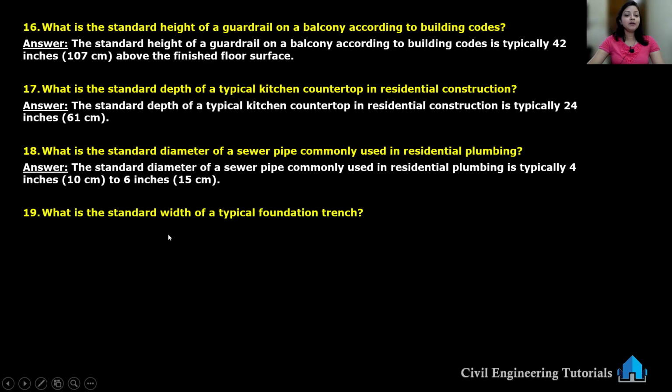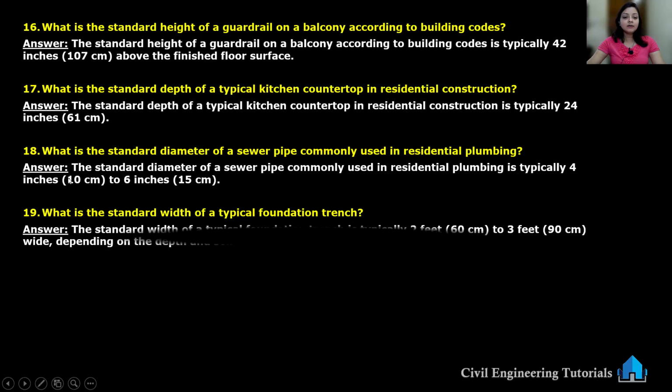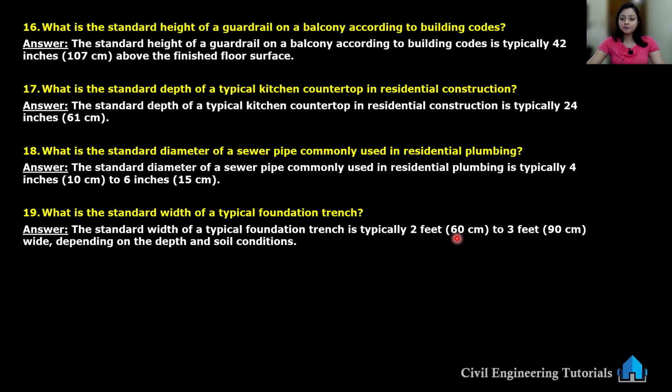Next, what is the standard width of a typical foundation trench? The standard width of a typical foundation trench is typically 2 feet or 60 centimeter to 3 feet or 90 centimeter wide, depending on the depth and soil condition.